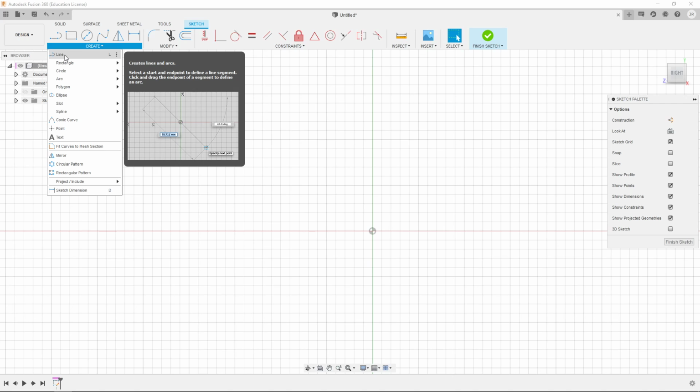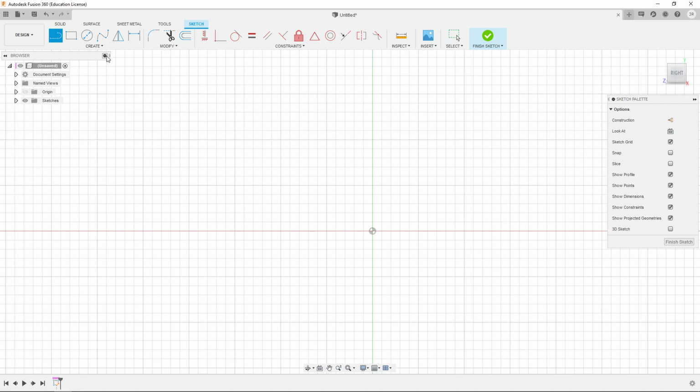When I click on the tool or use the L keyboard shortcut, our cursor changes. We have a little crosshair, and we have a little symbol next to our mouse. If you just hover in one spot, it says place the first point. The way the line tool works is we click the first point of a line, and then we'll see a temporary view of where it is and what angle it's at and all this other information. And we can continue to click points and make connected lines, or we can stop at any point in time, wherever our line happens to be.